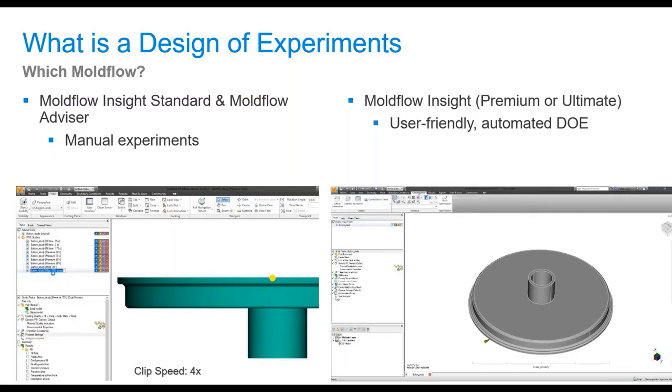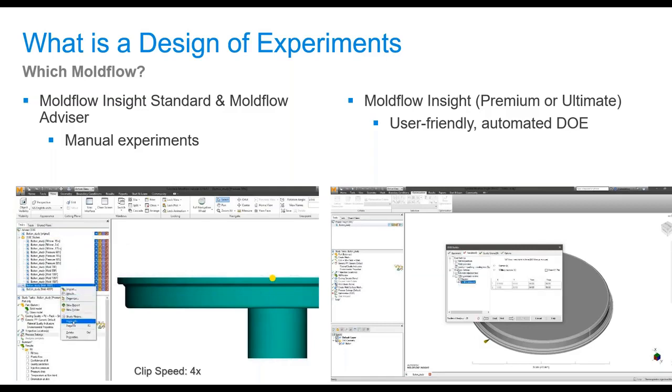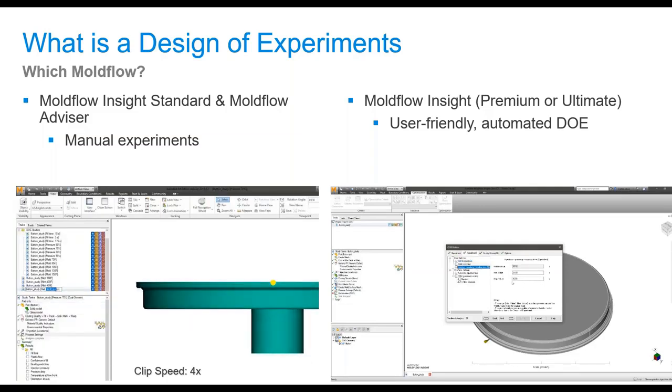When we jump into running a simulated DOE for injection molding, let's first understand how Moldflow works best. A DOE consists of running several versions of your original setup, and the number of runs is determined by the number of factors you plan to change. Because this is a more scientific way of analyzing their effects, the setup of each of those runs involves changing just one thing at a time while compiling on top of their changes. This means you may find you need to run 64 separate runs.